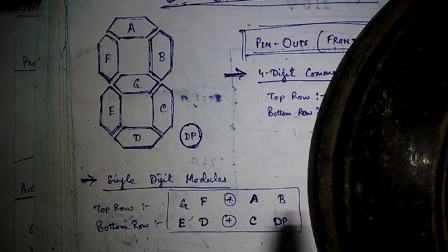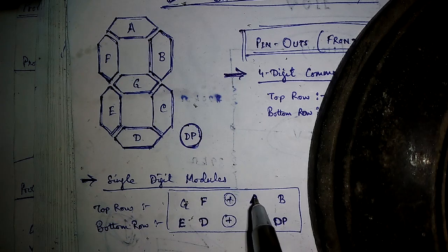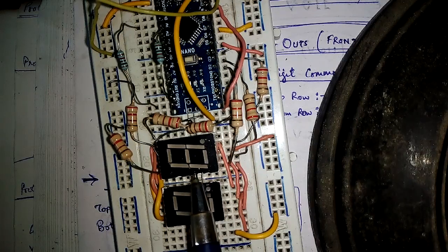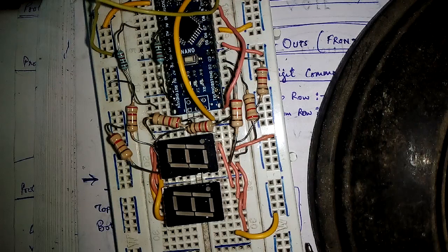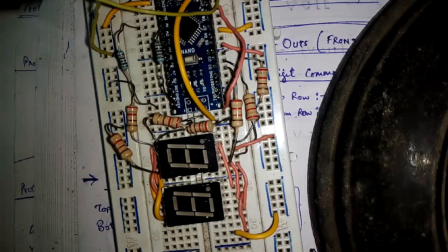You have two options. You can put resistances up in here but not in these segments, but I have put resistors on the segment pins but not in the digit pin. So that is of your choice, whatever you can do. I have connected two of these, but actually we will do only one of these right now because lighting up two of these is quite difficult, and I will show you how to do that maybe in another video. So basically, let me connect my Arduino now.